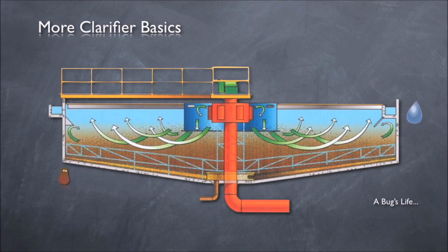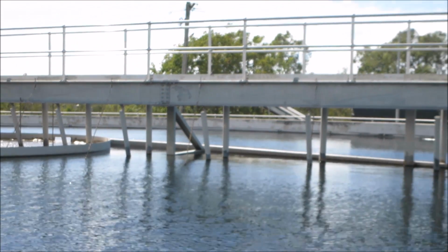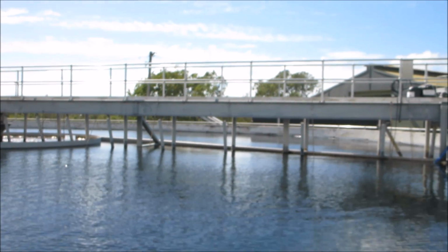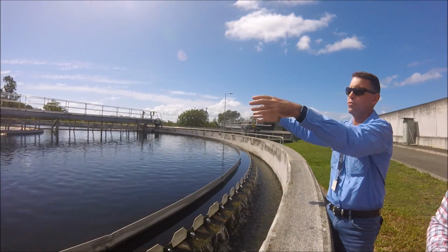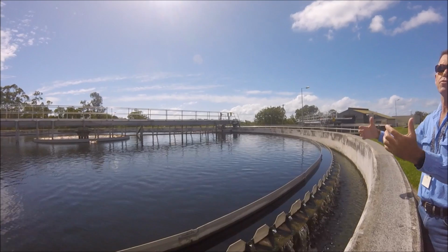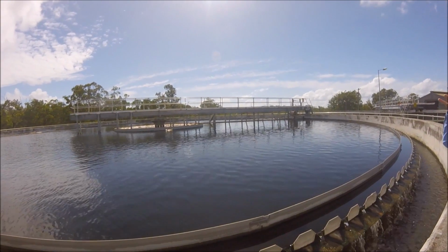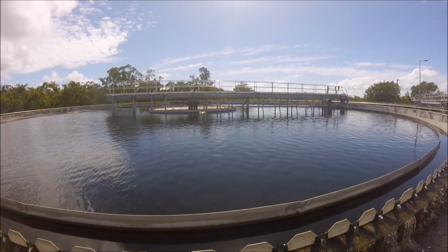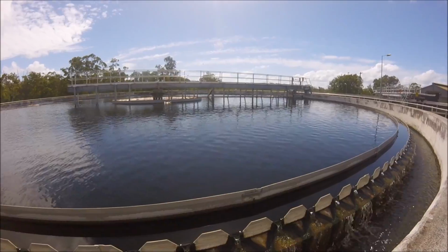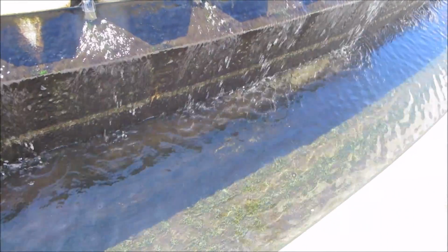After settling, the activated sludge is mechanically scraped from the bottom by the rake arms and pumped out through the bottom of the tank. This step is done carefully to avoid resuspension. The skimmer is used to remove grease, oil, and other floating materials on the surface. The density current baffle located on the edge of the tank before the overflow trench prevents the scum floating on the surface from entering the overflow trench. Although very clear, the water is not suitable for consumption.